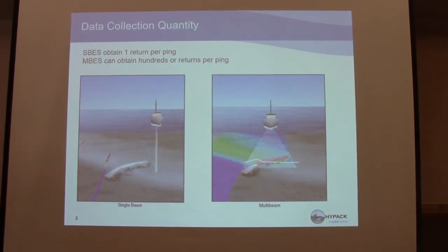Is that total swath width good data? No, not always. If they say that the sonar is good for 200 degrees or 180 degrees or 160 degrees, really the good stuff is inside of 65 degrees port and starboard.